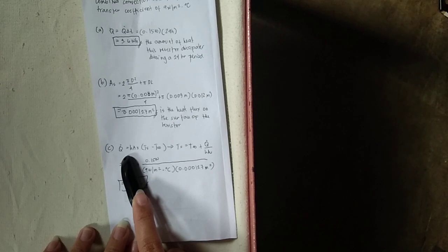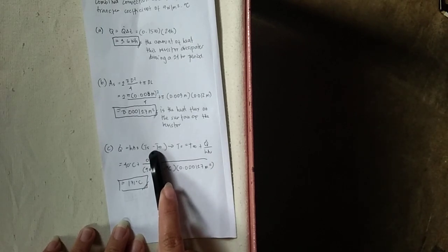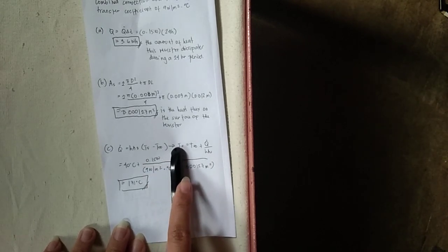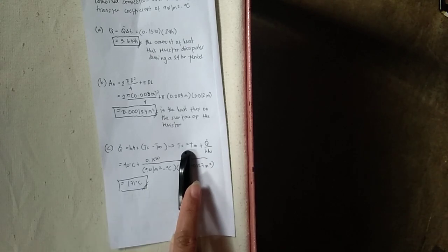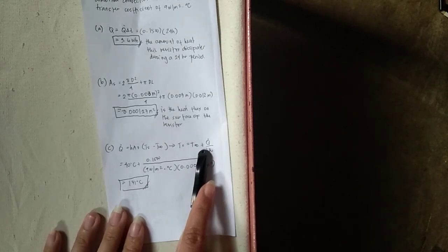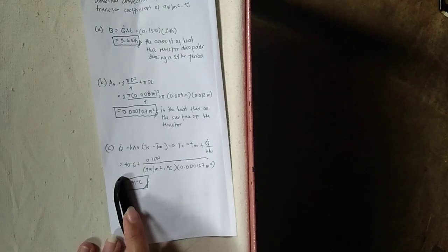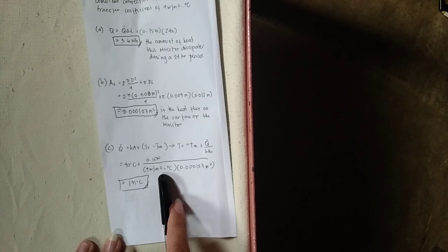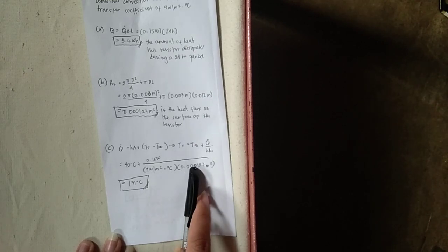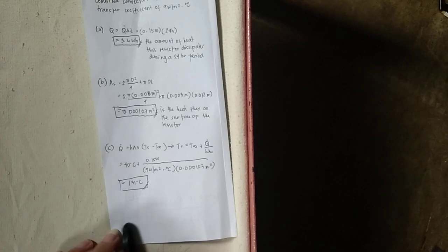Heat flow rate is equal to heat transfer coefficient times surface area times surface temperature minus temperature of free-flowing fluid. So surface temperature is equal to temperature of free-flowing fluid plus heat flow rate over heat transfer coefficient times surface area. Then substitute: 40 degrees Celsius plus 0.15 watts over 9 watts per meter squared times degree Celsius times 0.000127 meter squared, which is equal to 171 degrees Celsius.